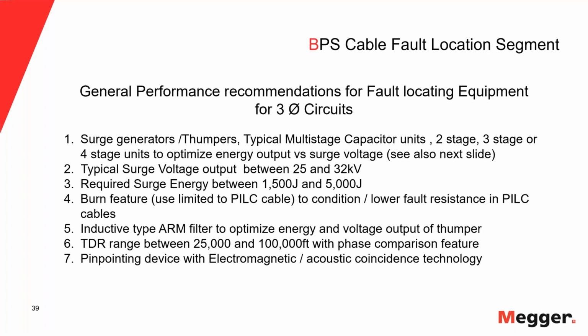So burning is a good feature when I have paper cables. And like I was saying before, it all comes together when I have a mixed cable circuit in a network, and I do the high pot because I get a high insulation resistance. I said you have to do a high pot, and if I get a high pot where it fails maybe